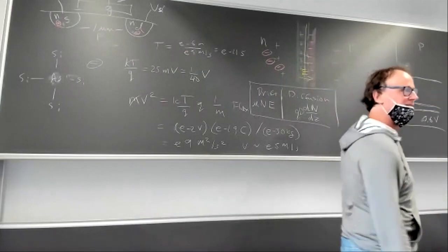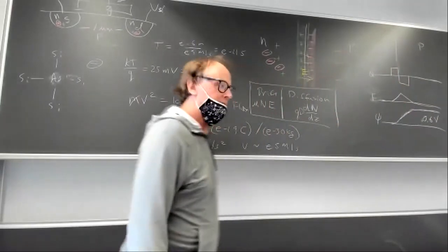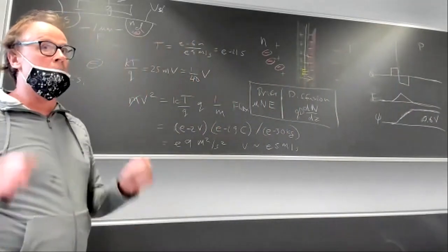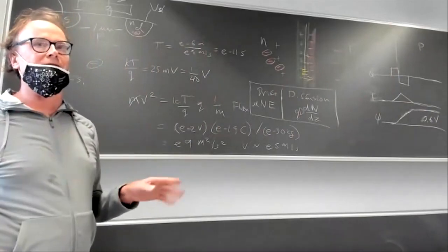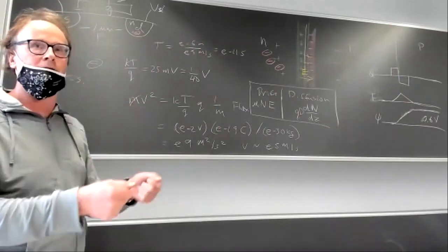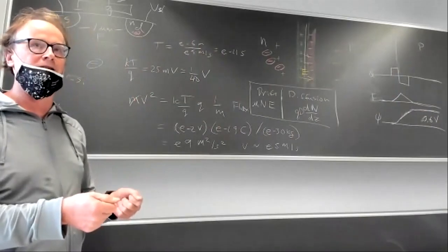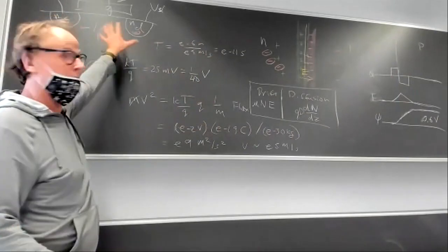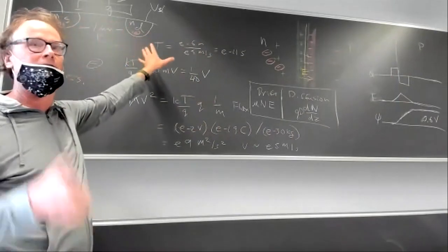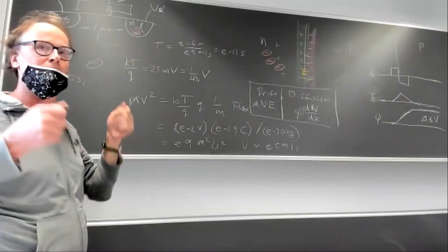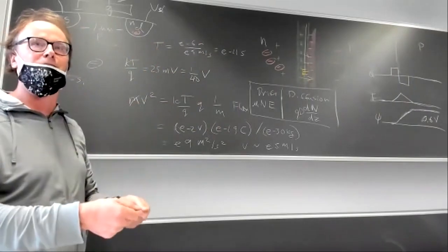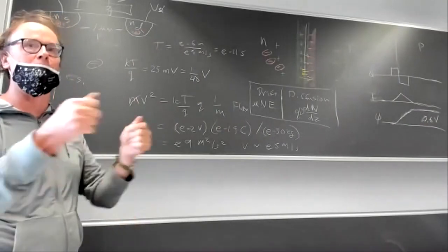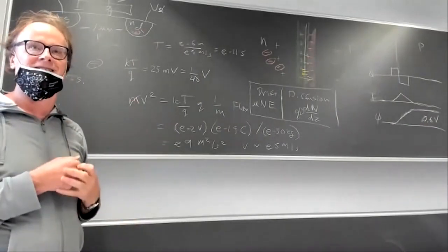I see. Okay. So it's net work, just in general. It's not the actual potential difference. You can't measure this potential difference. This is another confusing thing. You can't stick a voltmeter on there and measure this potential difference, because when you stick the metal electrodes on there, they also have their own junction characteristics, even though they're not junctions. So it turns out that you won't measure any voltage if you just stick a voltmeter on there. But there is an electric field in there, right? You just can't measure it by sticking a voltmeter on it.